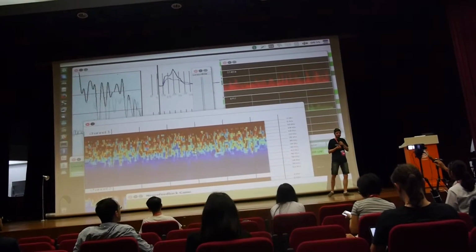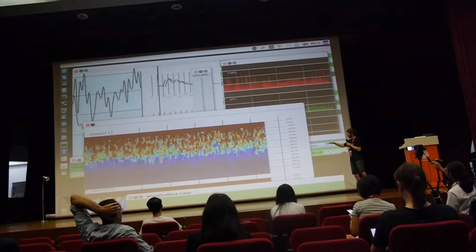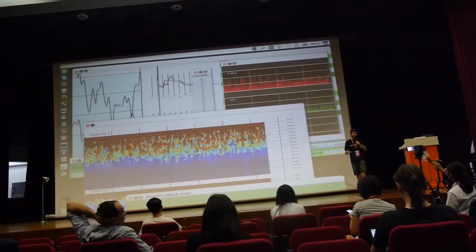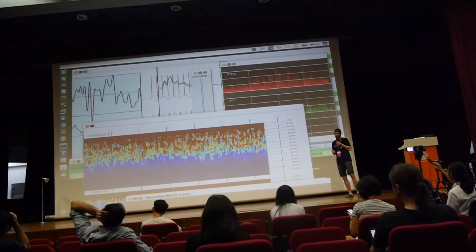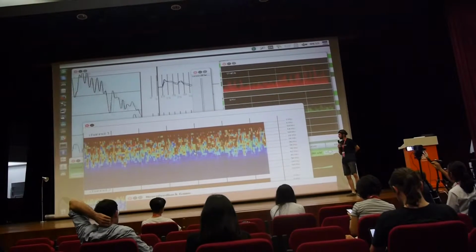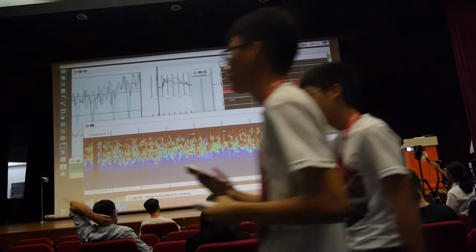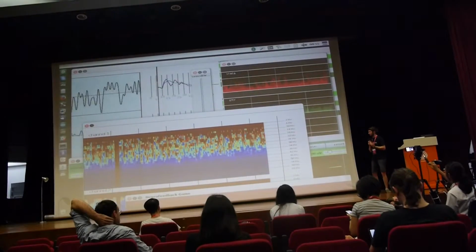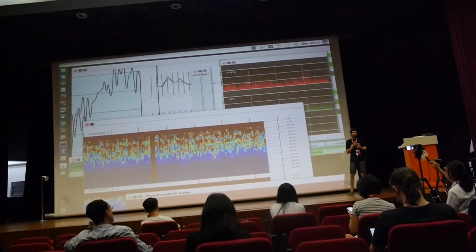But of course we sample more. So it's not like 80. You have the Nyquist theorem, you have double the samples, but we can go up to 1,300 samples per second. And this is also great if you want to do, let's say, classification, if you have a lot of data points, and also for discerning between noise and the actual brainwave signal.